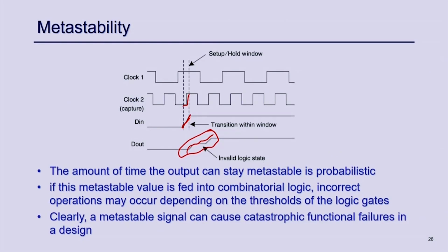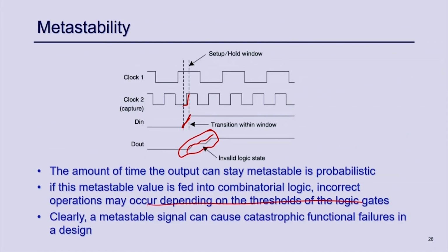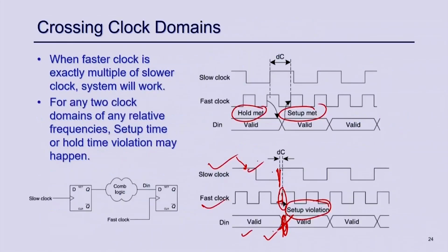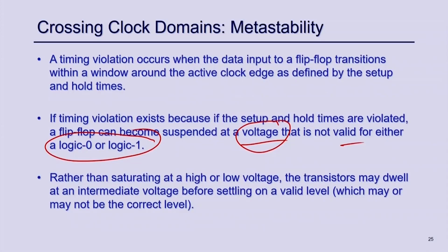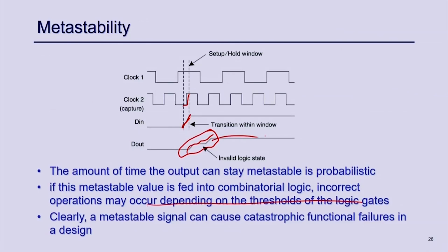So, that is not an expected state, right, and that is called metastability, and this particular metastability will go through this circuit following this, through the combinational circuit and the following gates also, right. So, this metastability will propagate and may propagate to the output. High voltage means 1 and low voltage means 0, right. So, it might dwell at an intermediate voltage, and it may reach some value, I do not know what value will come here, some state after some time, right.